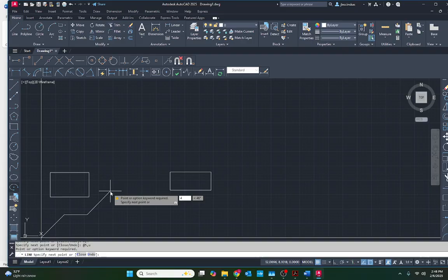Now, when you type absolute addresses, you can just type the dimensions in. When you type relative addresses, oftentimes, and off the top of my head, I do not recall exactly where AutoCAD requires this, but oftentimes it requires you to make sure that you're telling AutoCAD that it is a relative reference.